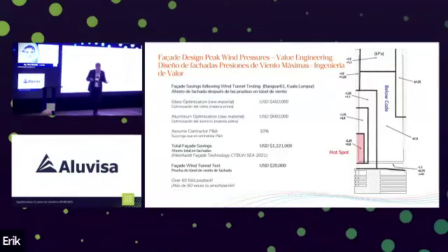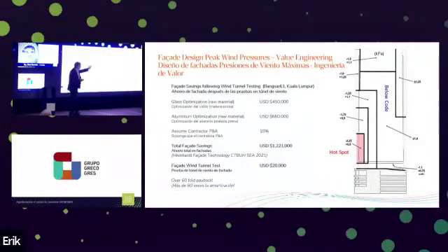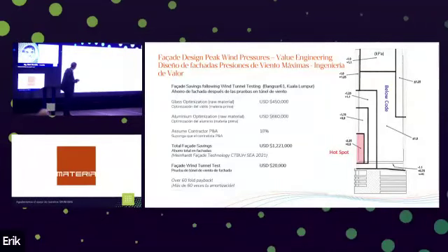And it's a quasi-static load where we're not including resonant components because of the high natural frequency typically on curtain wall facades. But what we do find by doing this empirical test is that a lot of the facade area is below code. And it does become a value engineering exercise.